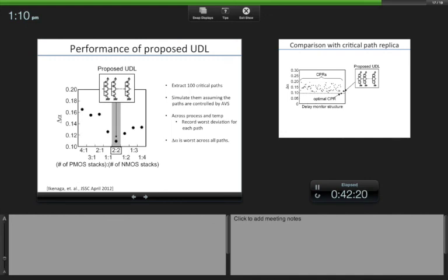Now, the previous paper by Nakai had a delay monitor which itself was configurable. You had some muxes and so on. You could change the proportion of NAND to inverter and wiring and so on. That configuration is different. You do it one time. For a particular product, you figure out what the configuration setting is and you do it, and that's it. That is not part of the feedback loop at all. Feedback loop per chip is just adjusting the supply voltage. Here, the configuration is done not by adjusting the number of stages of the delay line, but because it is a completely digital approach, they create that and multiply it with a factor alpha. That alpha you can configure and adjust. So that's basically what they do here.